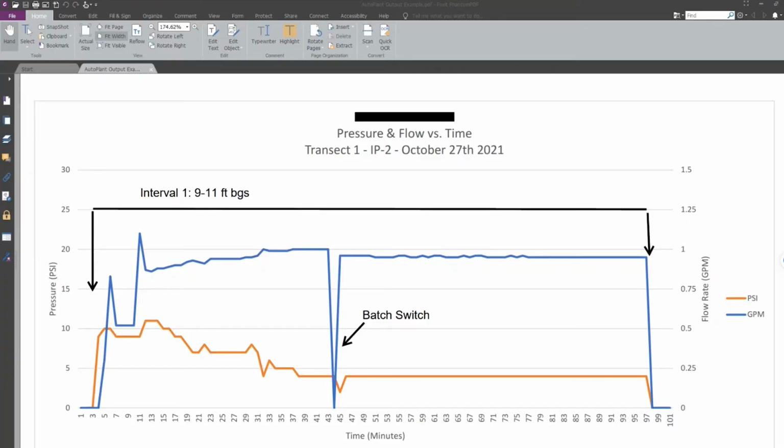And that data can be displayed in a very similar manner to this, where you can see a baseline value, and then you can start to see creep upward, and actually the groundwater table subsiding while the crew broke for lunch in the middle of the day, and then once they came back and started pumping again, you could see the groundwater come up again to the high water mark for the day, and then settle back down once they had finished injections. So we're still working that data into a display model.